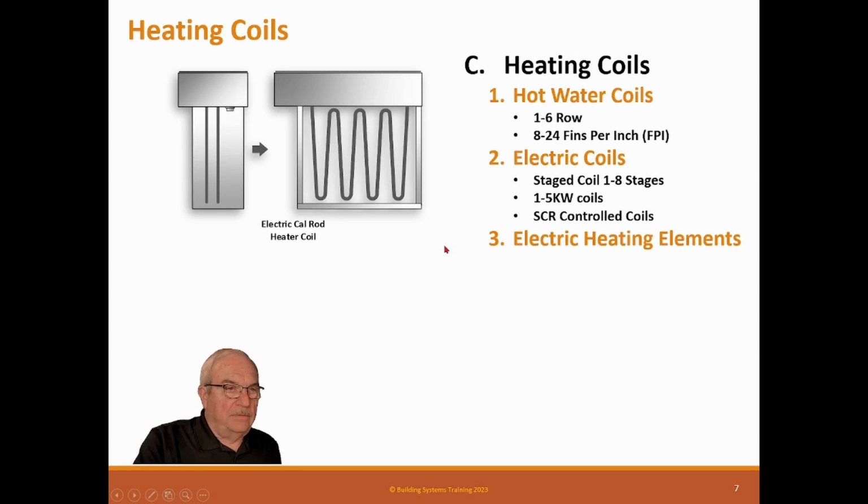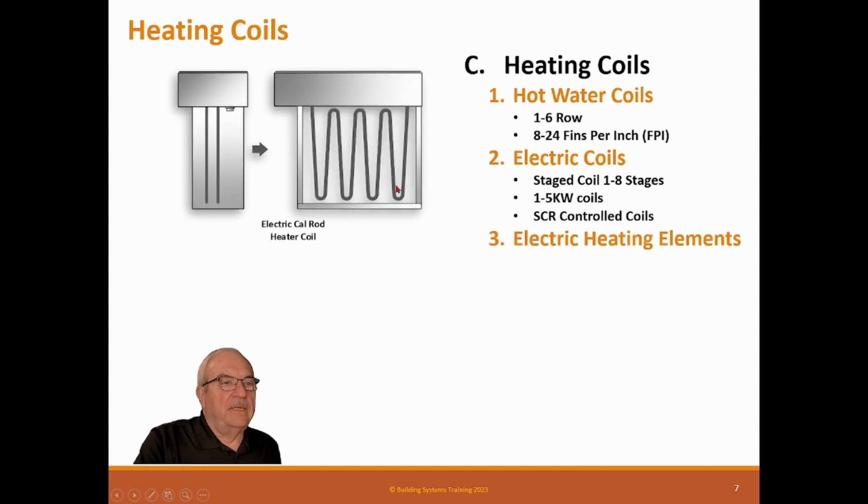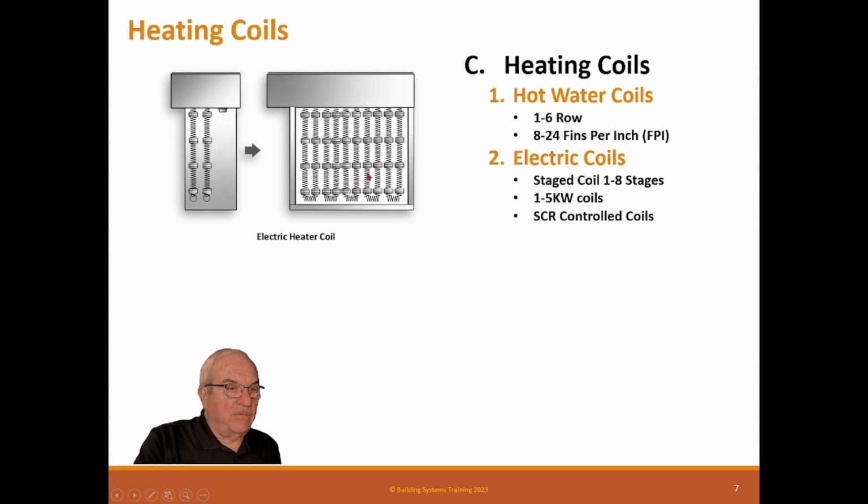Electric heating elements. That one before I showed you, this one here is a standard open coil. So the heating element's open to the air. This is a Calrod heater where the actual wire element is encased in another element. So this is a tube. And what it means here is this one's much less susceptible to that velocity problem, or if you have contaminated air. So this coil here, if you have lint, it'll burn it. If you have paper in it, it'll catch it on fire. So you have to be careful because these get red hot. So you can't have contaminated air here.